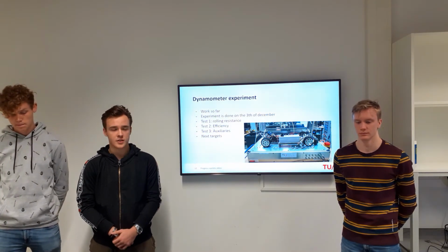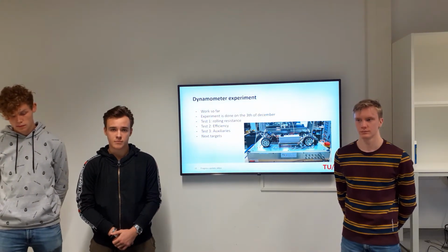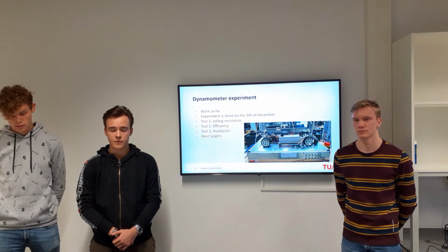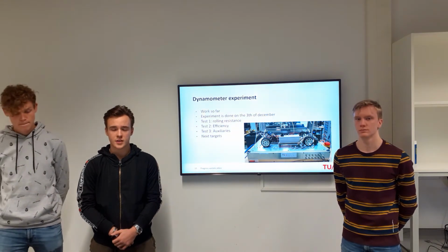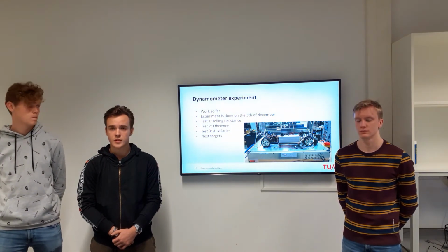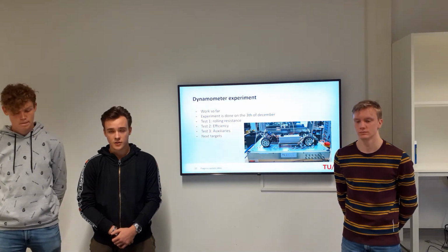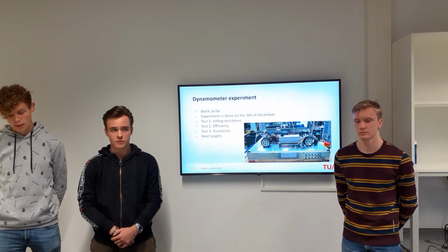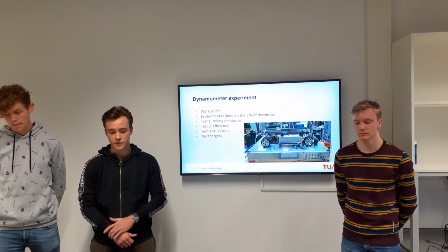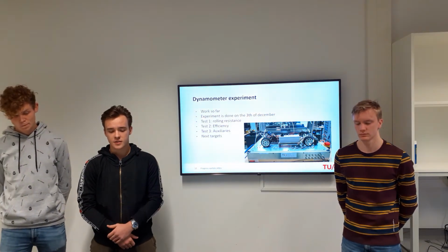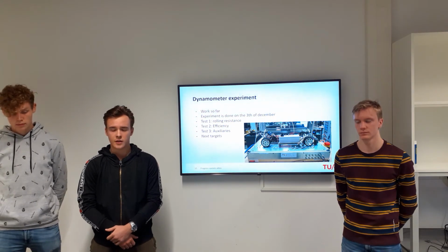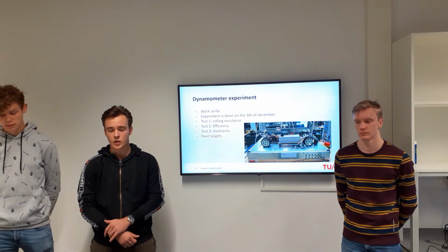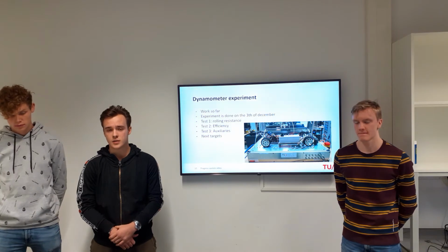The first test is already done by the crew of the dynamometer itself. This first test is about knowing the rolling resistance on the dyno, because the dyno is a tire on metal, so the rolling resistance coefficient is different. The second test is all about knowing the efficiency of the drivetrain and making a tank-to-wheel analysis.